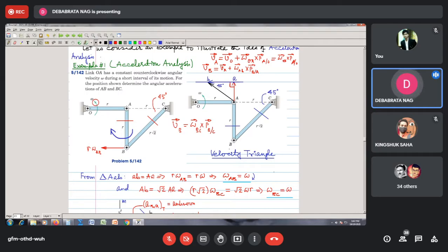Okay. Now secondly comes this link, this BC link. Here you see this is the absolute velocity of point B. Now if you mentally place this absolute velocity here, then obviously this velocity can only be realized if this link is also rotating in this direction. So as a result, I find that this link BC also has a clockwise angular velocity. So you see the driven crank is rotating in the counterclockwise direction, but at this instant the connecting rod is rotating in the clockwise sense, as also the driven crank is rotating in the clockwise sense. Okay. So up to this part, the entire velocity analysis is done.